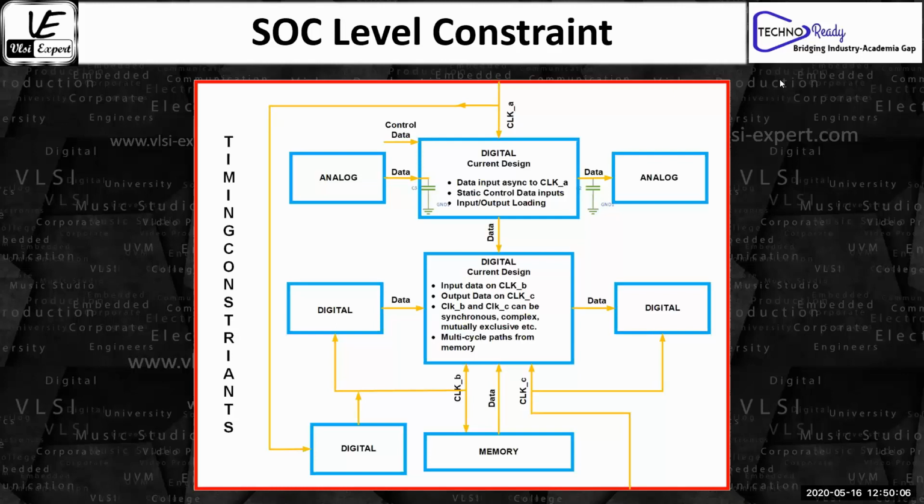So in your design, what can happen is, at the top level, let us suppose there is only one clock. In this particular case, clock A and clock C are both coming from outside from different PLL sources, so you can say these two are asynchronous clocks. But when it comes to clock A and clock B, clock B is generated from clock A. So from the top level, if I come up with the flat design, I can easily figure out that clock A and clock B are both synchronous in nature. They have a relationship, generated with a certain digital block.